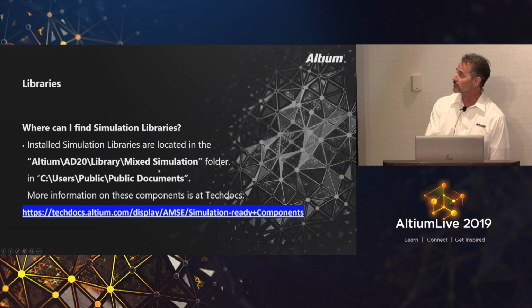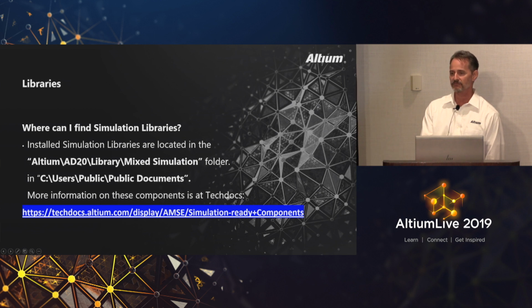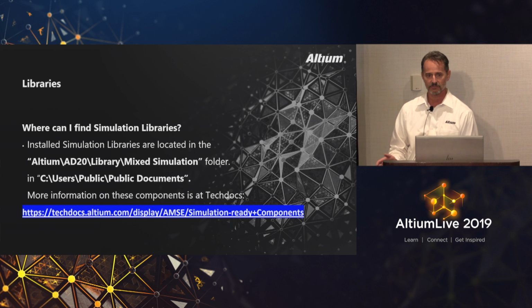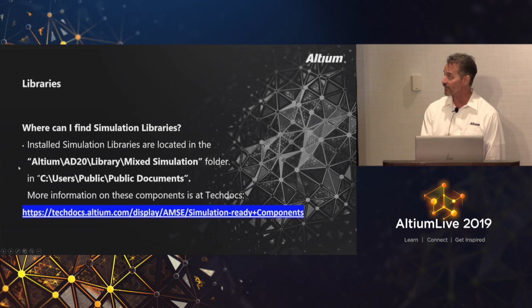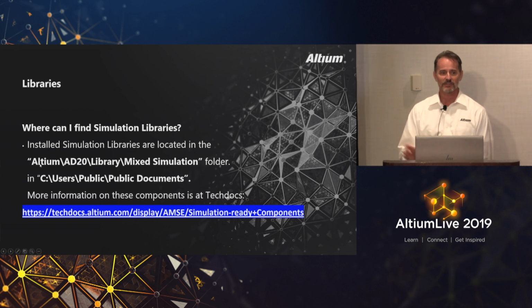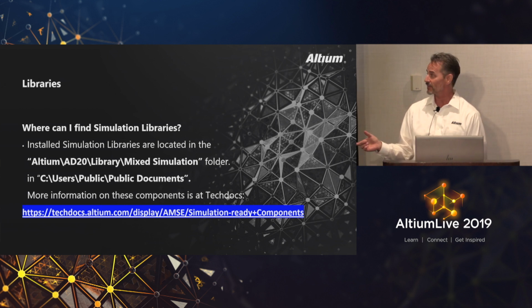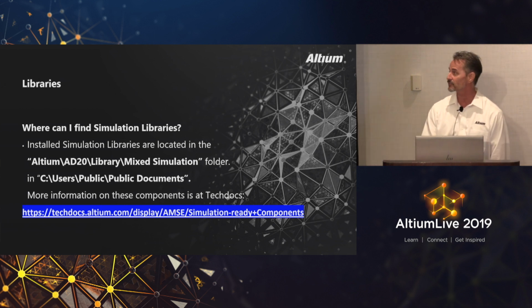Now, when you are experimenting or making your own examples, just a word of caution, don't put your examples in the version-specific folder, because when you uninstall Altium, it'll wipe that folder out, and you don't want to inadvertently lose your examples. This Altium folder is pretty safe. I just put a subfolder in there with all my projects, and the uninstall won't touch that one, but anything that has a version number on it, you have to be careful.